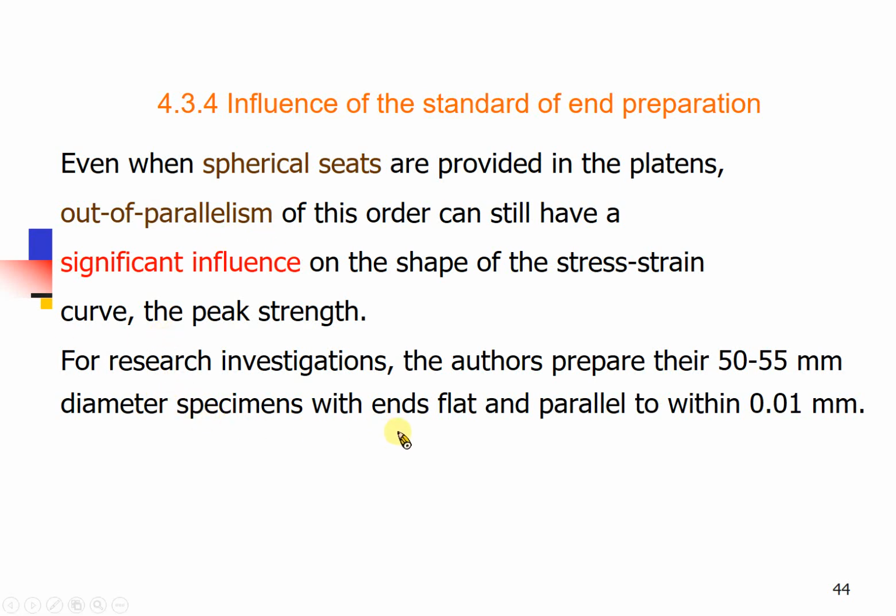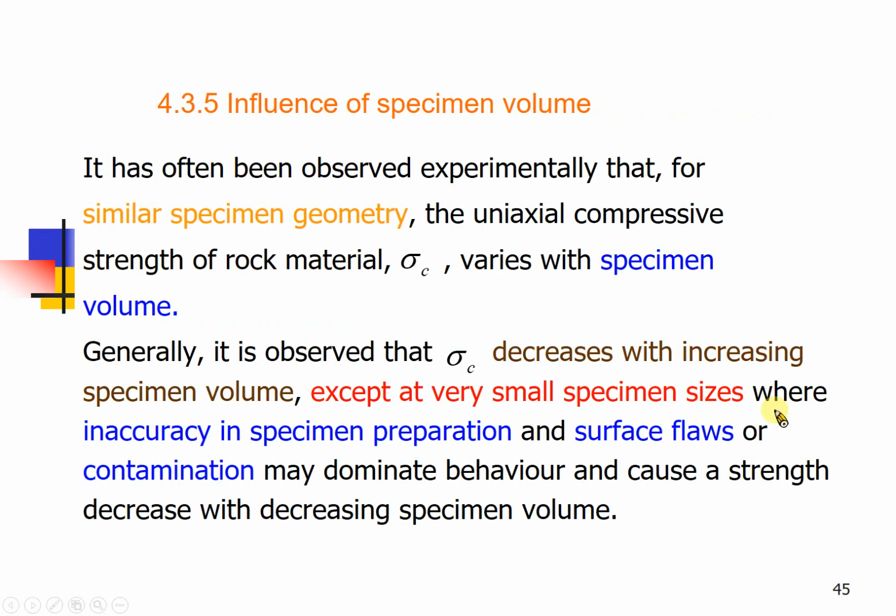For research purposes, it is suggested to have higher precision if you focus on rock test research. This I already mentioned to you yesterday or several weeks ago. This is the influence of the specimen volume: the larger the specimen volume is, the smaller the strength will be.